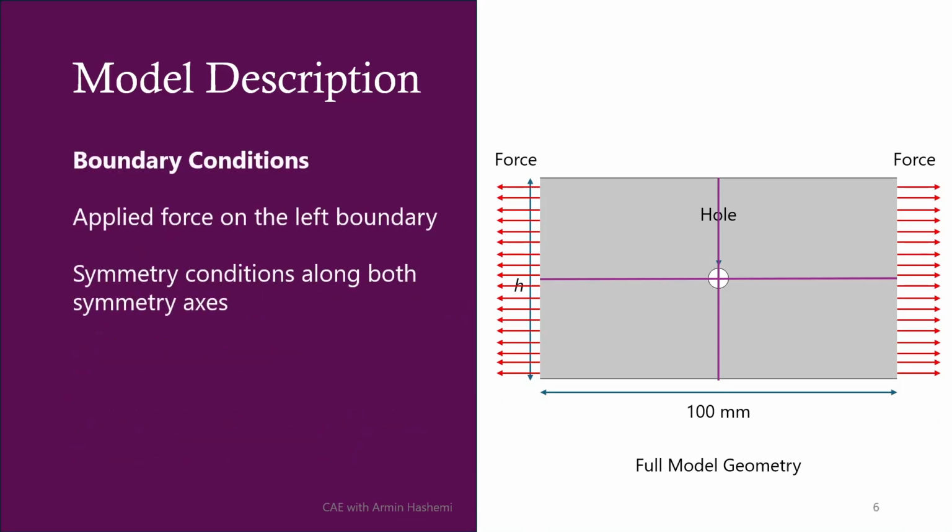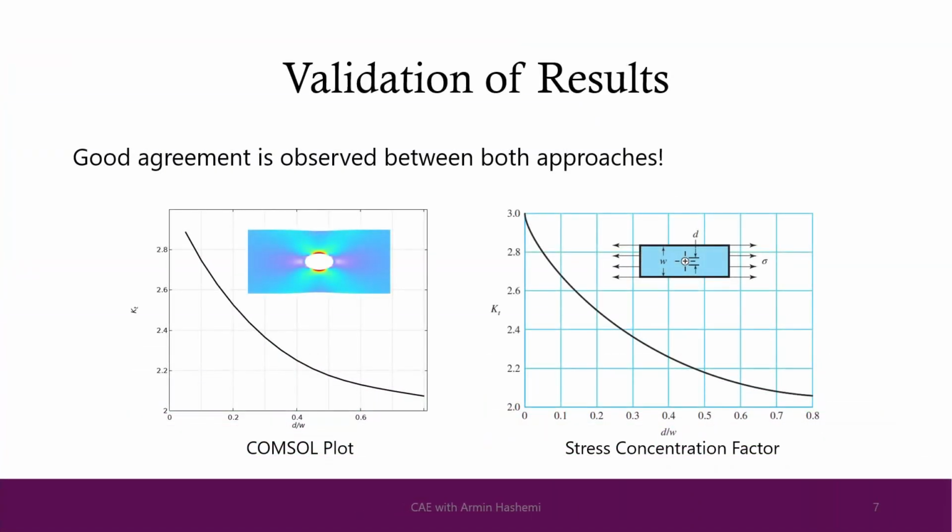Two boundary conditions are applied: a symmetry condition along the symmetry axis, and an applied force on the left boundary of the model. Finally, we compare the stress concentration factor from a reference book, which will be introduced later, with the COMSOL solution. The results show good agreement.